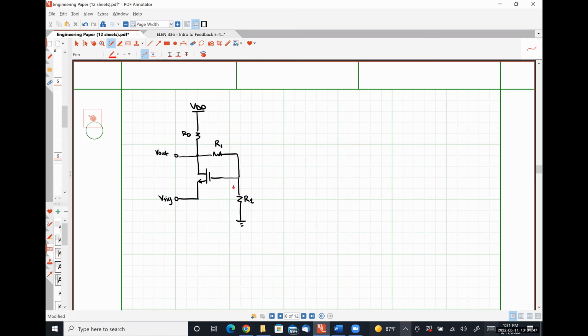I am simply going to acknowledge that the voltage drop over resistor R2 is my feedback resistor, and the gate source voltage is Vi, my input signal to my open loop amplifier. Okay. So effectively just pointing out how this is set up so that we can figure out what our feedback network is and all that kind of good stuff.